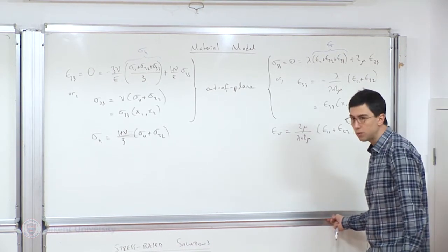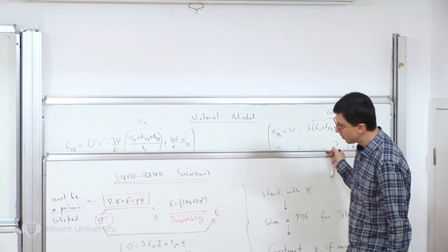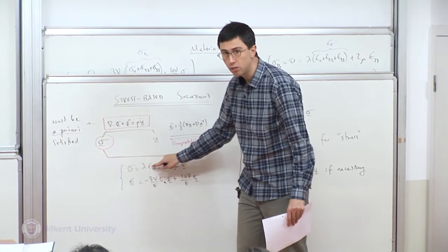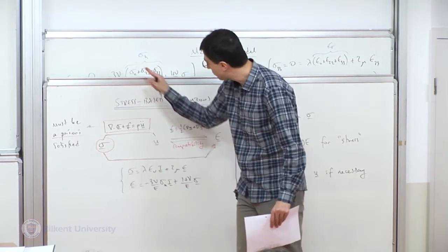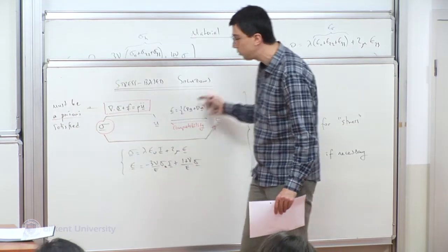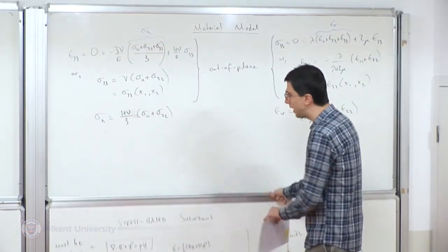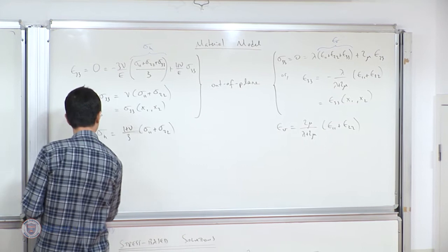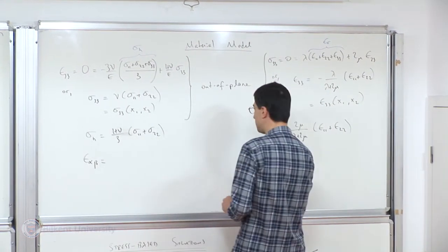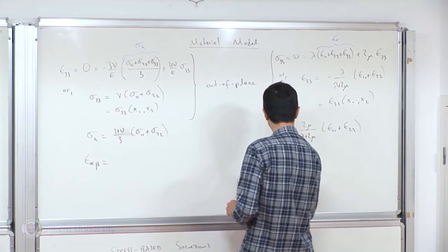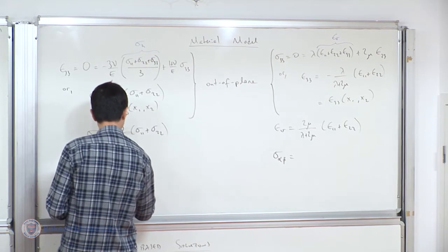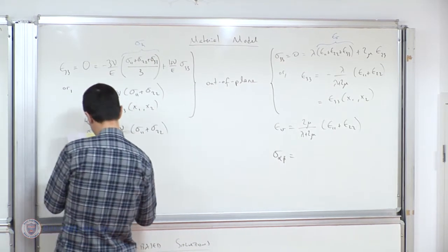Okay, so now what I'm going to do is, just to remind you, for plane stress, I'm going to plug in epsilon v there in terms of only 1,1 and 2,2. And for the plane strain case, I'm going to plug in sigma h only in terms of 1,1 and 2,2. And I'm going to get an expression respectively for epsilon alpha beta and here for sigma alpha beta. And those expressions are, after only a little bit of manipulation, okay.